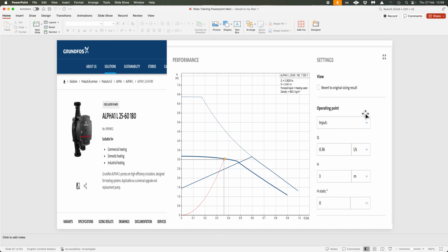And you can see here that we had 0.36 litres per second of requirement. I calculated this out as an example. You can change this in the software from meters head to kPa or whatever it is once you've calculated an index circuit out. You put that into the system, and you can see it actually builds a pump chart for you, and it's stating that for our 22.3 kilowatts of heat loss with a 3 meter head of resistance, that would be 30 kPa or 30,000 pascals, we have got a pump chart here.